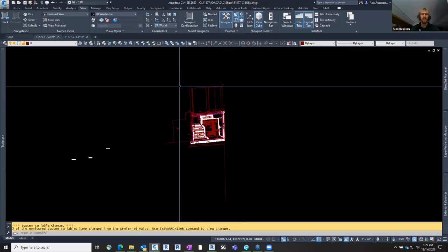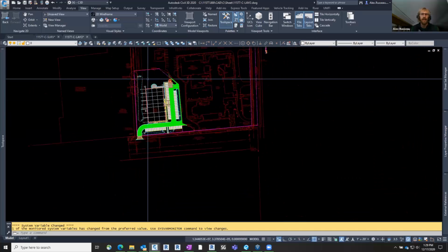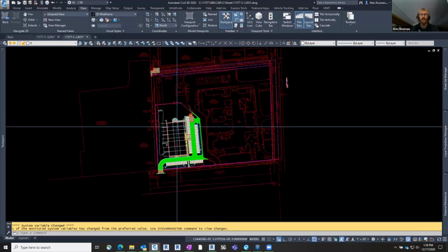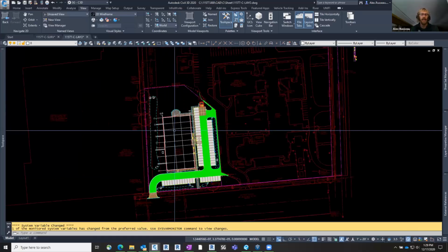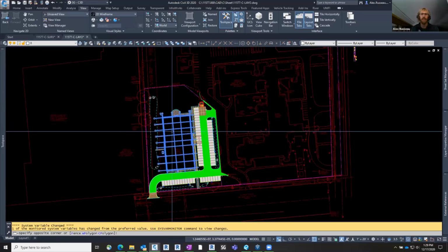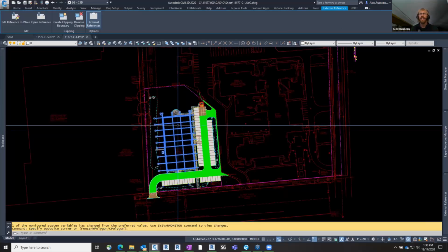So the other file that I'm going to be using here today is a layout file. This file I've already coordinated with, since this project's pretty much done. I've coordinated with the architects and we've already got the building model. They've exported it out for me. I was able to locate it on the site, which is probably one of the first steps that you'll ever want to do: give an export to the civil engineers so they can understand what that building is. And the number one thing I can always recommend: export with grids.